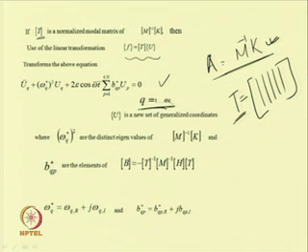In this way we have transformed this coupled equation for the sandwich beam to a set of uncoupled equations, and in this uncoupled equation one can note that the coefficient of u_p is a periodic term. That is why this equation is a parametrically excited system, but here we have a number of forcing terms associated with this term depending on the number of modes we are taking in this solution.